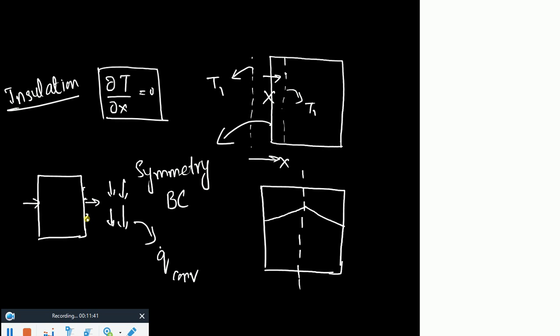Remember the surface balance condition, the energy balance on a surface. You remember that? I told you that whatever is coming in, the same would be going out. If you have a closed system, let's say a control volume type of thing, then there can be energy storage, there can be some kind of energy generation. But if you have a surface, you can't store energy in that. You can't produce energy in that.